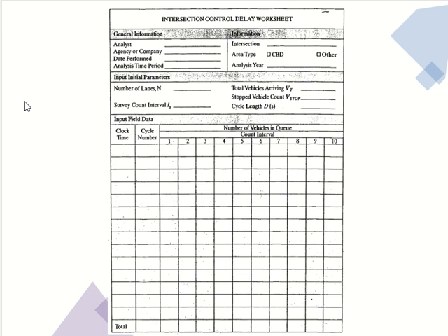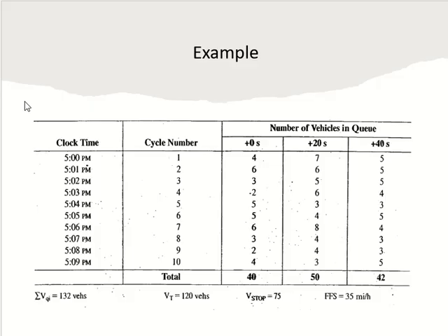Once the 6 values are done, the new cycle has started, and they will start from a new row. We said the cycle is the time from the start of the red to the start of the next red, right? So the observation should also start from red. You don't break any cycle. When the signal just became red, the cycle has just started, and you will start from the start of the cycle. Clear? And then he will write the observations and so on.